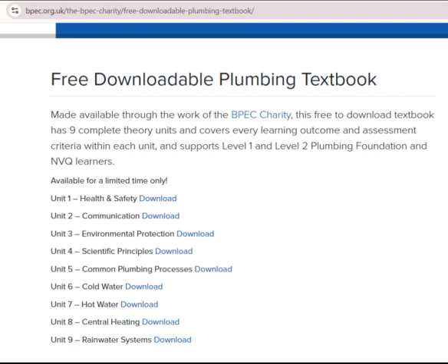Fully pumped systems give a greater choice of system design, especially when positioning components such as the hot water storage cylinder. No longer was it necessary to have the cylinder higher than the boiler, because gravity circulation had been eliminated. Other benefits are greater choice of boiler position and quicker hot water heating times. These are just a selection of the benefits of the fully pumped system.